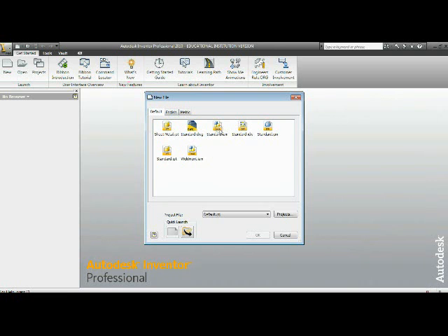These are part files, and of course we have sheet metal up here, we have a weldment assembly. The standard IAM is the standard assembly model. Then we have the standard drawing, which is basically an AutoCAD type file. Then we have standard.idw, which is a two-dimensional drawing that's created from the three-dimensional part.